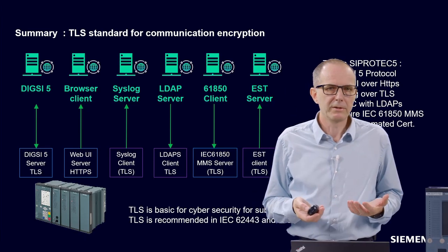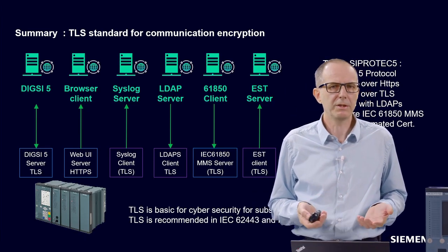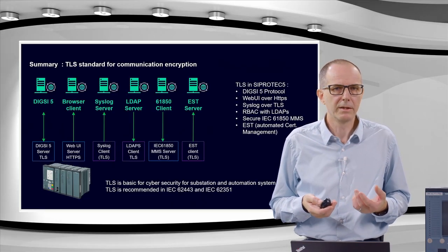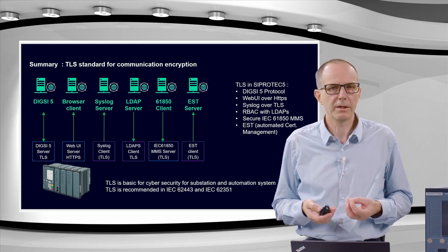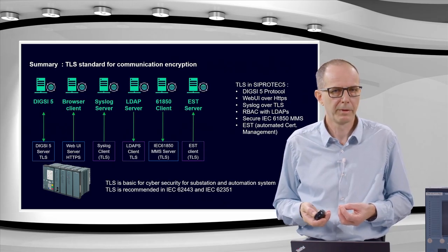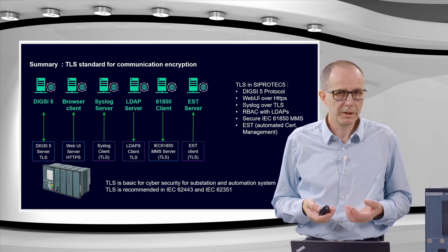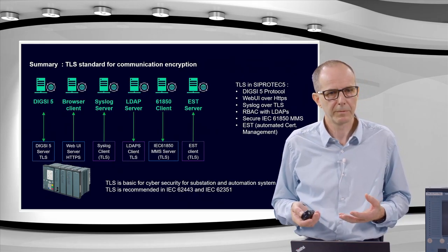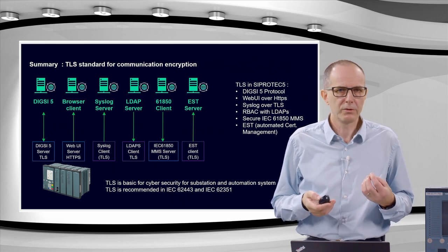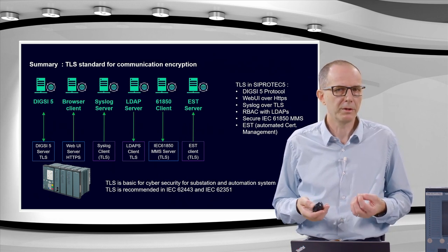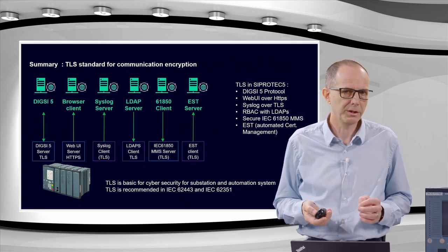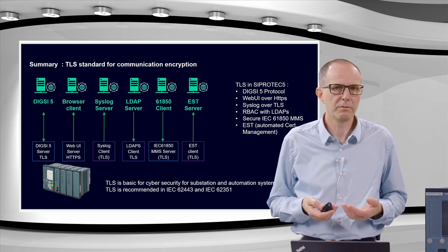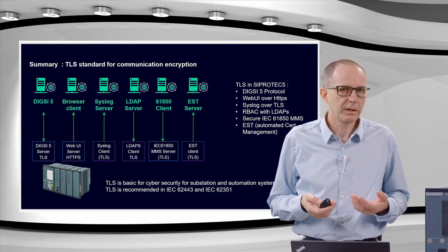Why should we talk about TLS? Because it's used as a state-of-the-art method for encryption. And we have implemented this everywhere in SIPROTEC 5 where data integrity is necessary. For the engineering tool DIGSI, the communication protocol is encrypted via TLS with mutual authentication. For the access to the web page, HTTPS is encrypted via TLS with server authentication. In case syslog message wants to be protected from manipulation, TLS can also be applied.